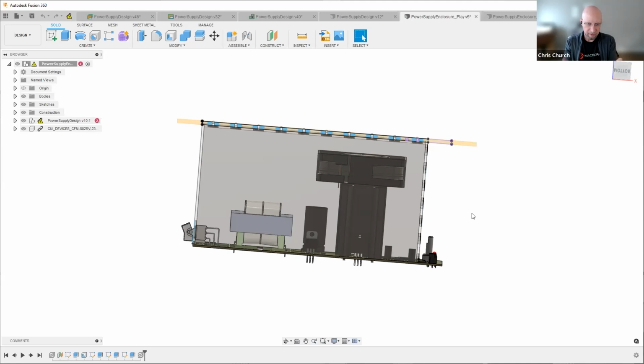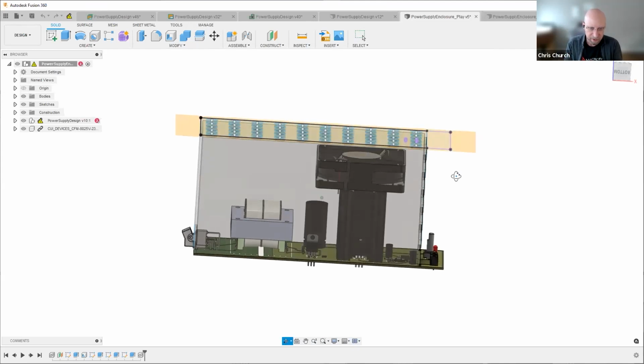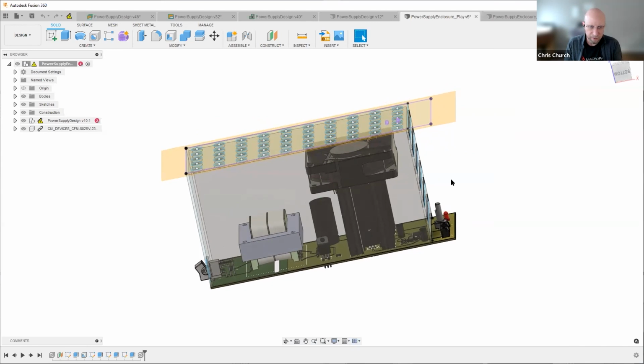We're looking at what's clearly a punched and folded metal enclosure, and that's the easiest way to add those threaded inserts. They add them during the punching process before they fold it, and then we've got really good screw inserts there, and it should be really easy for us to assemble that.